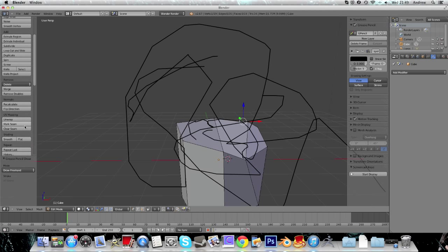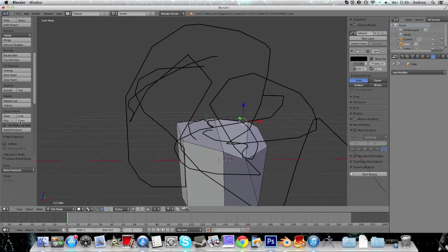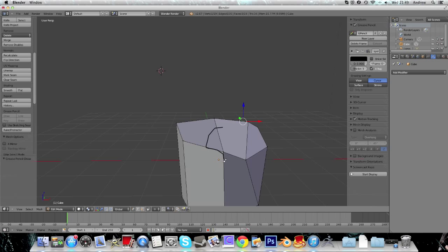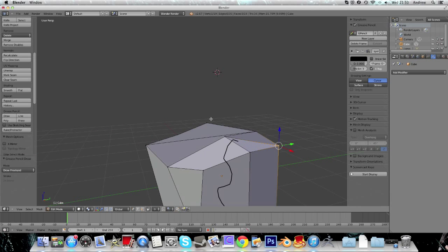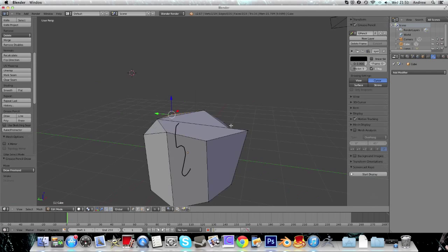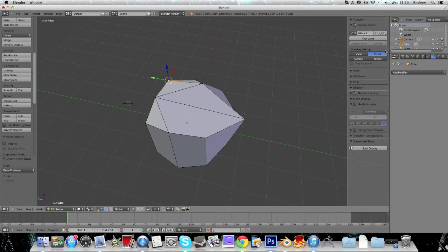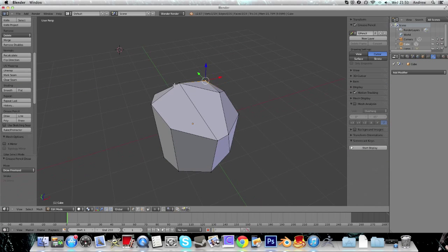There is actually a delete option over here on the left. There's probably a shortcut as well, but if I go to erase, then we actually rub some of this out, which is useful. But if we want to delete the whole thing, then we can just click the little X here. And if I press D to draw again, but with cursor, then it's going to draw around where my cursor is. So I can look around in 3D view and see my drawing. So that's all really useful. We can also turn off X-ray so it's not visible through our shapes. And we can change the thickness and colour and so on. But they're fairly basic settings. So that's quite useful as well.